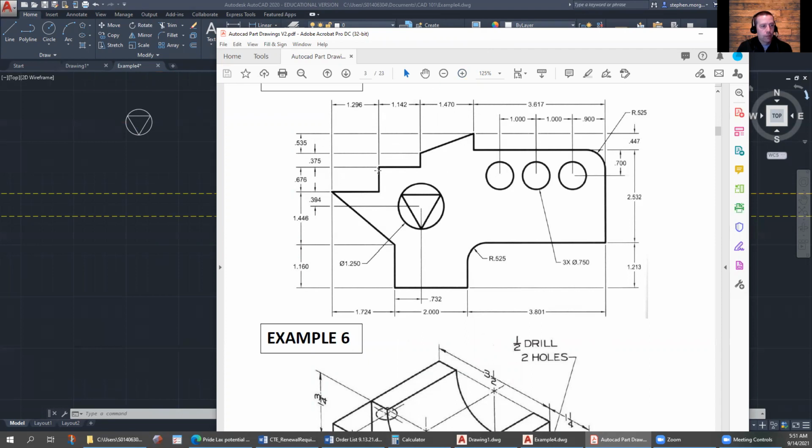So the one thing you want to really pay attention to is that all of your lines are actually snapping to corners, and that your construction lines and actual object lines are horizontal and vertical, and you're not missing your snap points. That can throw off students, and once you get off on some dimensions, then when you go to dimension your drawing, the dimensions aren't quite accurate.